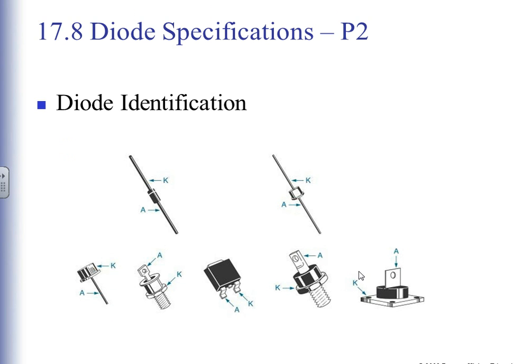Okay, I look at this guy, where are my 2 leads? Well, one lead is the heat sink, so I'm grounding it. A for anode, K for cathode, A for and, positive. So my positive side's the anode, my negative side is the cathode, and I'm stuck with those words because that's how I did it in tube technology.